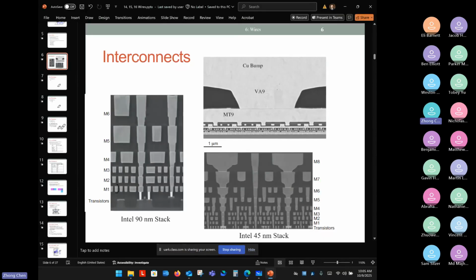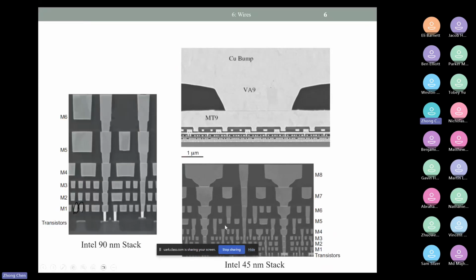You see this line and this line. I still need to have a full screen here. Okay, there's two: this is the metal, this is the metal, and this is the interlayer dielectric. So between these metals, there will be a capacitor associated with the different metal lines. The metal itself will also have some skin effect and some capacitance associated with that, but mainly it is the metal to metal, the metal one to the metal two. There's some capacitance between the metal one and the metal two.